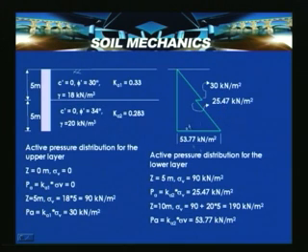Now, at Z is equal to 10 meters, we have vertical stress, 90 kN/m square plus 20 into 5. This 20 is the unit weight. Please note that the unit weight has also changed here. So with that 190, the entire layer above acts like a surcharge at this level, where Ka2, which is 0.283, into 190 yields 53.77, that is the ordinate.